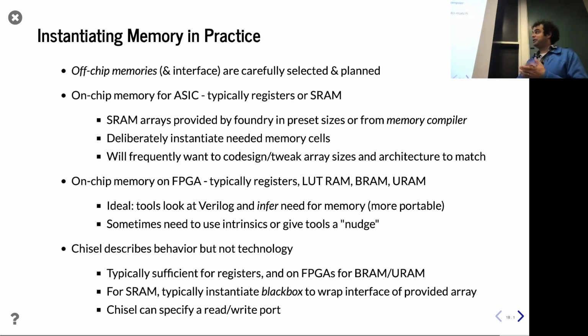I spent some amount of time in Chisel previously making the Chisel Verilog of memories such that popular FPGA tools would infer BRAMs automatically. Is it guaranteed? No, but it makes it more likely, and I'd rather people do that than try to manually use macros to get a BRAM for sure. Once again, in the spirit of make the tools do the work.